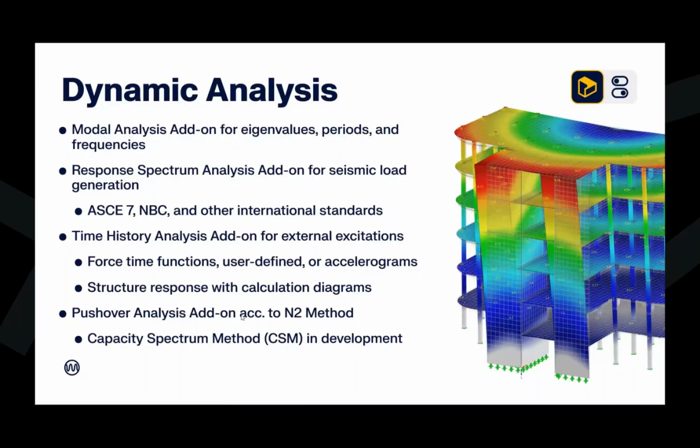So if we are interested in carrying out a seismic load generation, we would want to utilize the response spectrum analysis add-on. Within this add-on for seismic loads, we do have the codes implemented here, the ASCE 7, the NBC standard. And with the response spectrum analysis, this is applicable to any structure type.